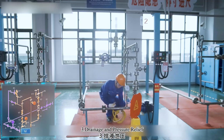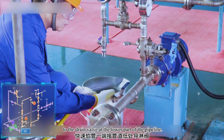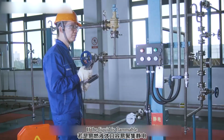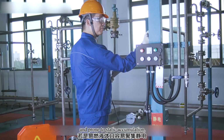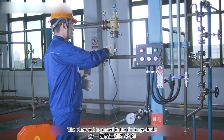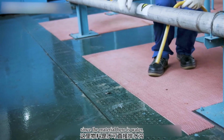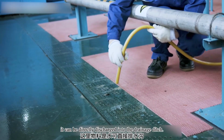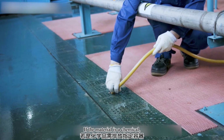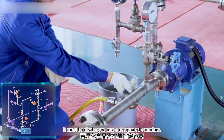Third, drainage and pressure relief. Connect one end of the quick hose to the drain valve at the lower part of the pipeline. If the liquid is flammable and prone to static accumulation, the container must be grounded during discharge. The other end is placed in the drainage ditch. Since the material here is water, it can be directly discharged into the drainage ditch. If the material is a chemical, it must be discharged into a designated container.